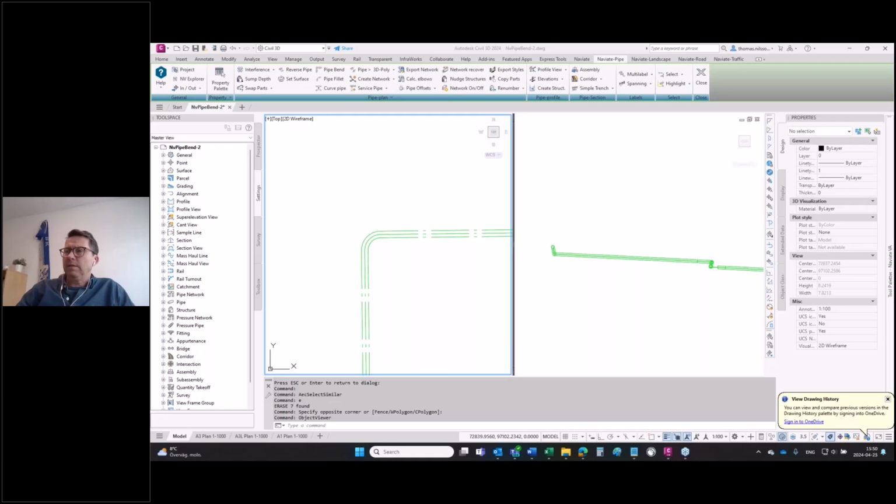Yes, in this way we create the same structure as the original structure in between the pipes. Which means that in this method we can actually run the commands that Caroline showed, offset pipe, we can run pipe elevation tools and so on these pipes, so we can change the slope afterwards.